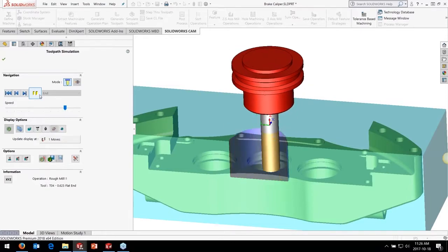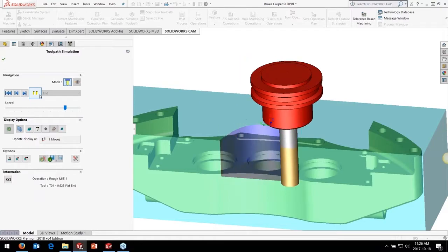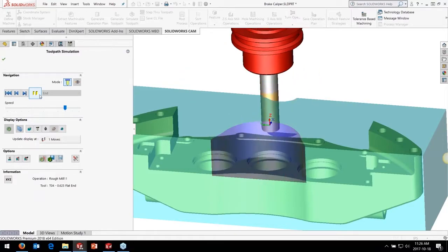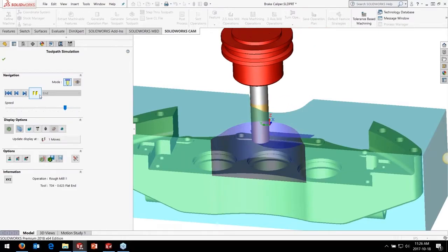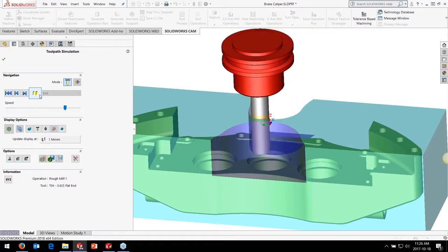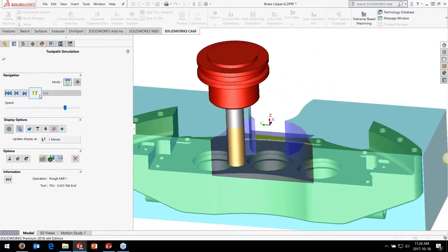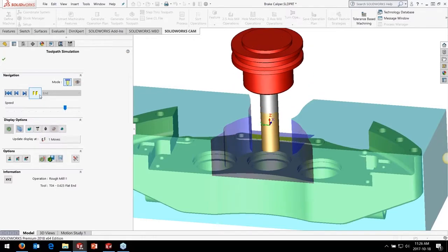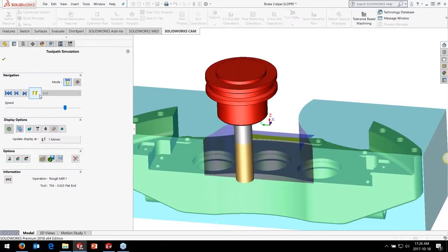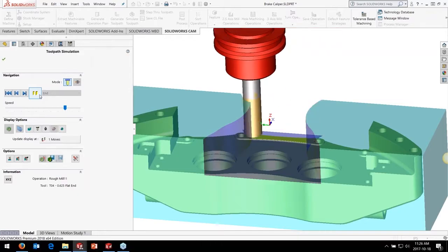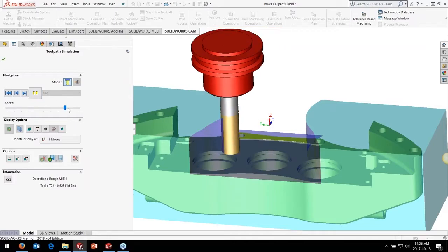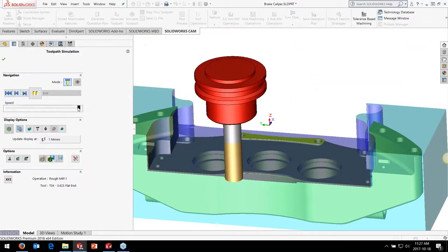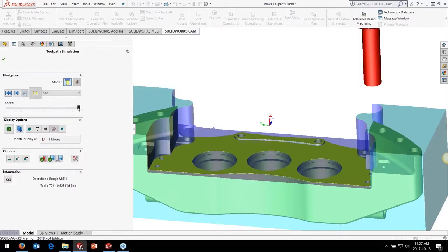So I'd hit preview, and now I've got some high-speed milling toolpath that will clear this out as fast as possible, but also reduce the wear on my tool. We're not focusing the wear and the heat just on that bottom portion. We're distributing it across the full flute length, so we get better tool wear because we're not going straight into material and causing wear on our tool. We actually get better machine life because we're not rattling those bearings as much in the spindle. So we get a much more effective, faster material removal in roughing here.